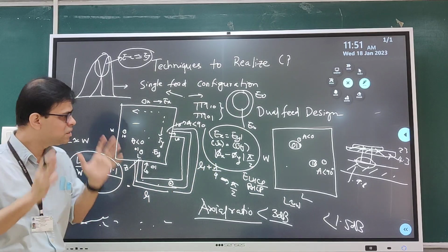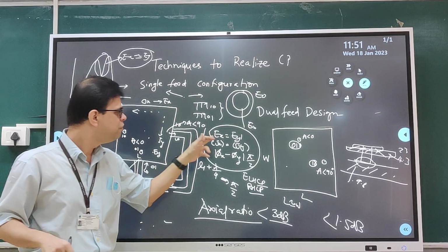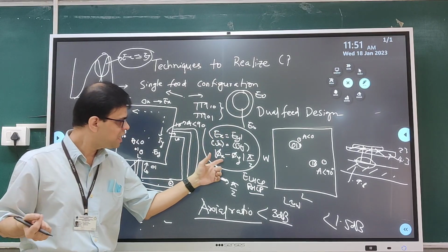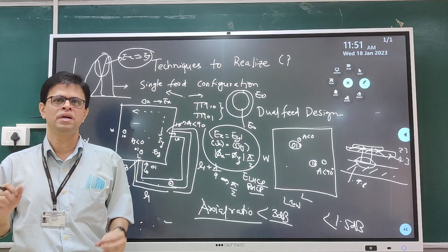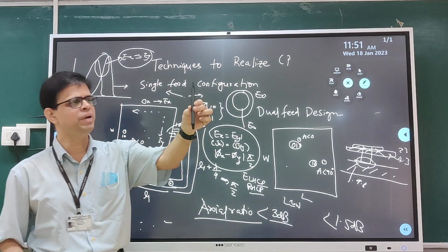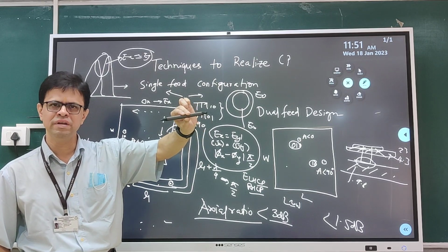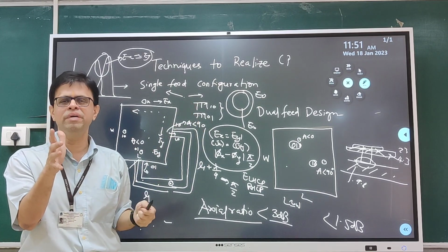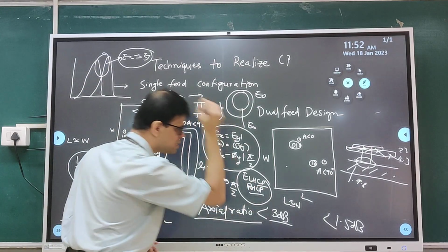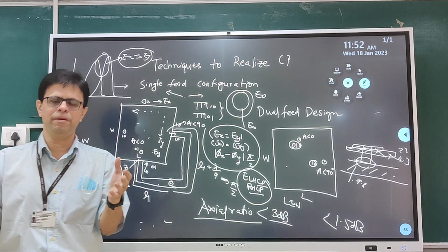So a circular polarized measurement in the ideal case should be done with respect to Ex and Ey, where the amplitudes are matched as well as the phase difference has to be judged. There is a set of equations using which you measure the power level in two orthogonal planes over a band of frequencies. Using those equations you can find out these LHCP and RHCP waves, and then you can plot them.